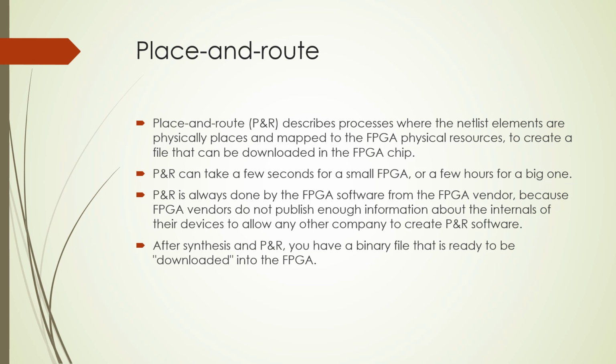In this technique, you place all the elements based on rules in the placing and routing step, and then they are mapped to the FPGA physical resources.